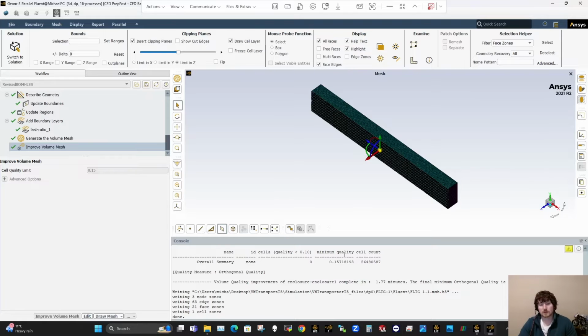So very good mesh quality on it. About 56 odd million cells. So you do want a nice bit of RAM. 128 gigabytes minimum for that. You'd want about 256 though for comfort, but 128 is the minimum.